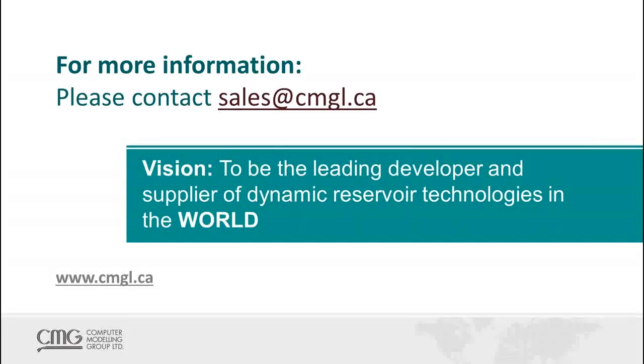The first question is from Franklin, and the question is, what are the main factors in terms of geomechanics to consider when choosing GEM or IMEX for unconventional simulation? Well, number one, the geomechanics capability that we have is only in GEM. It is not in IMEX right now. But in terms of getting started with geomechanics, you don't have to go crazy with complete detail. We need to have Young's modulus. We need to have Poisson's ratio. And actually, you can get started looking at things like drawdown sensitivity, stress-dependent perm sensitivity, just with that initial case.